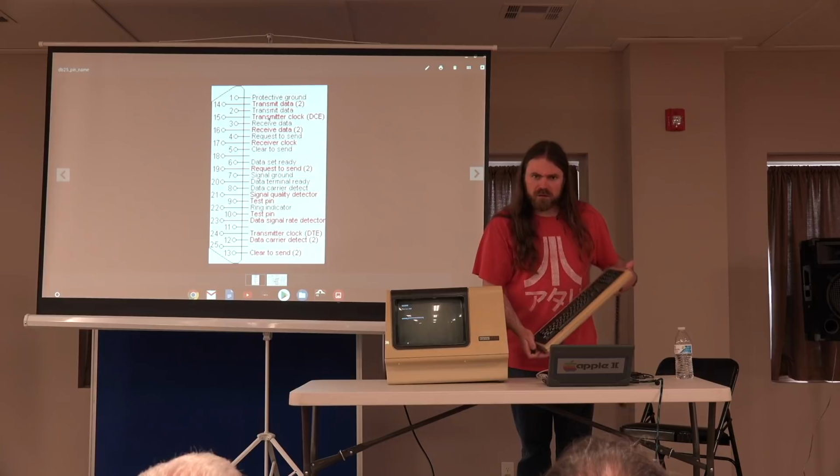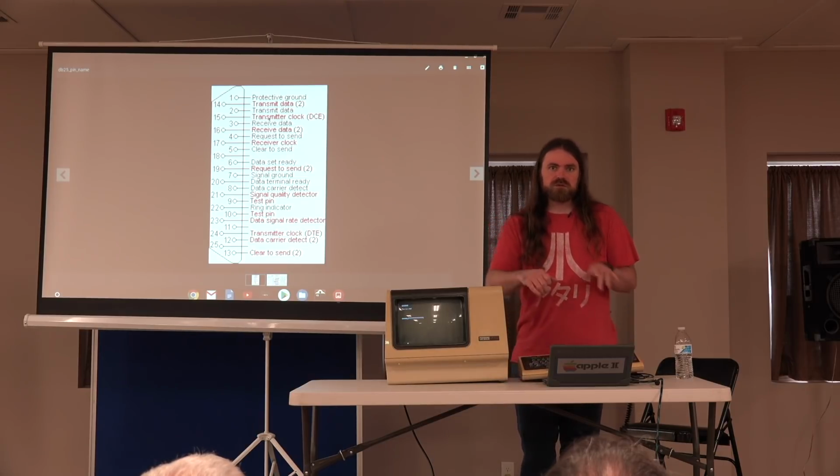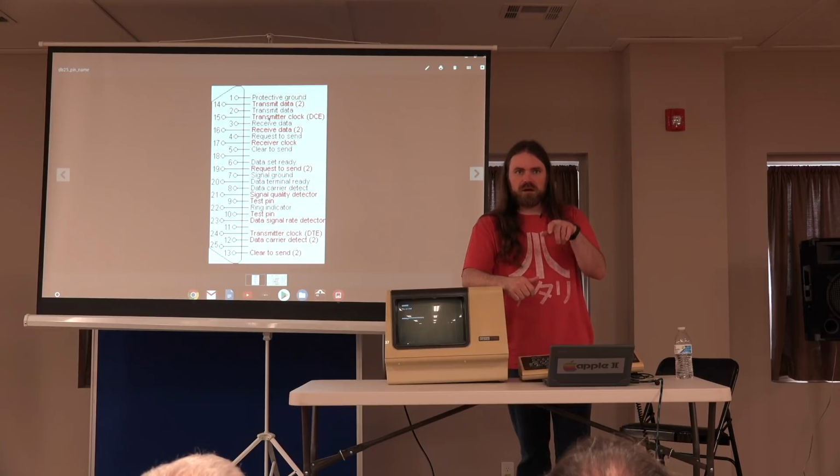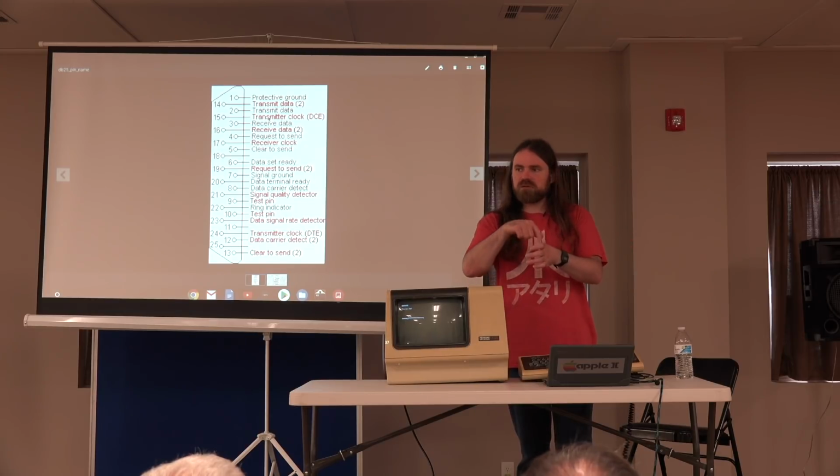Other types of keyboards, like on the Wyse terminals, tend to use standard little micro switch circuit board mount switches. They clip into a little frame. Those are standard little switches that you can scavenge off some other keyboard to fix it, or I think they still make those. The little plus-shaped actuator is on the top.